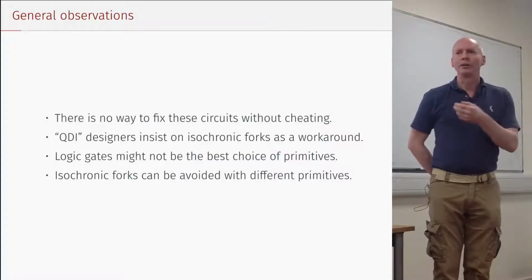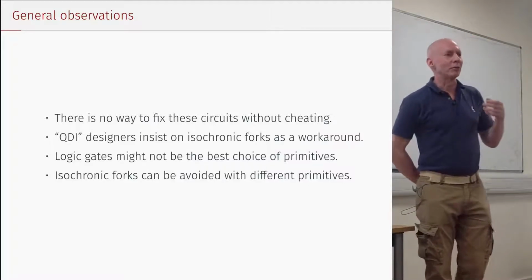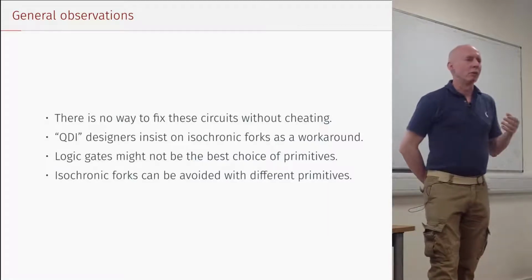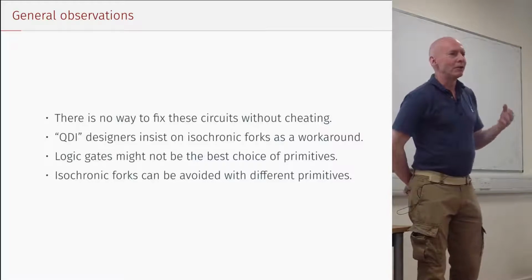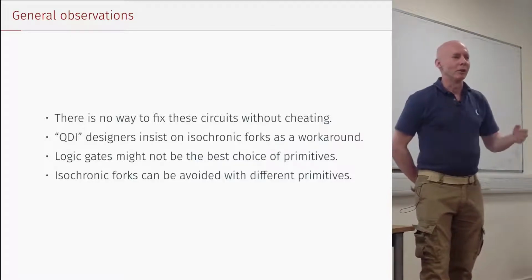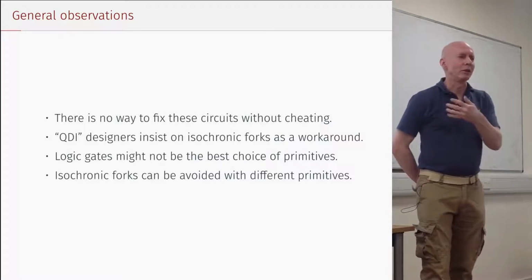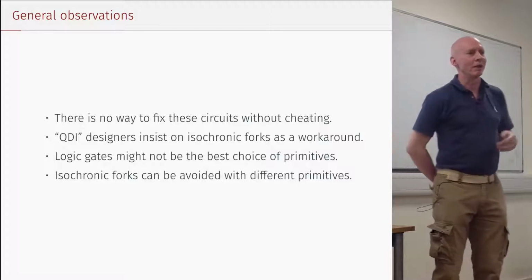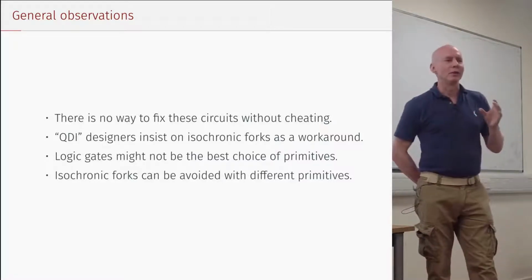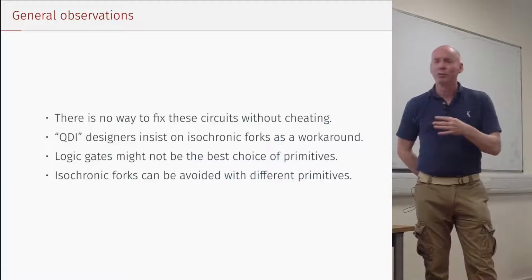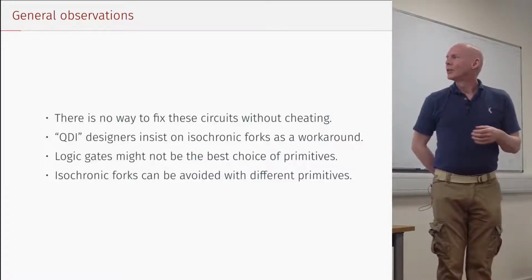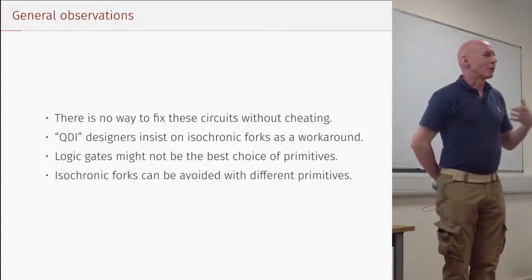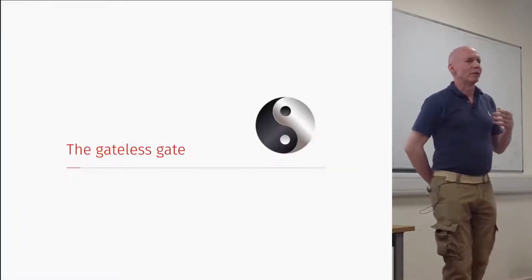The right way to do this as a delay-insensitive circuit would be using a dual rail code, because you can't take the absence of a yes to mean no. Right. So you'd have one wire for yes, one for no, and then it wouldn't solve this problem with isochronic forks that I've mentioned. You would still have to do some of the same stuff that I'm going to talk about now to get around it. So anyway, I was going to talk about these other primitives than logic gates.